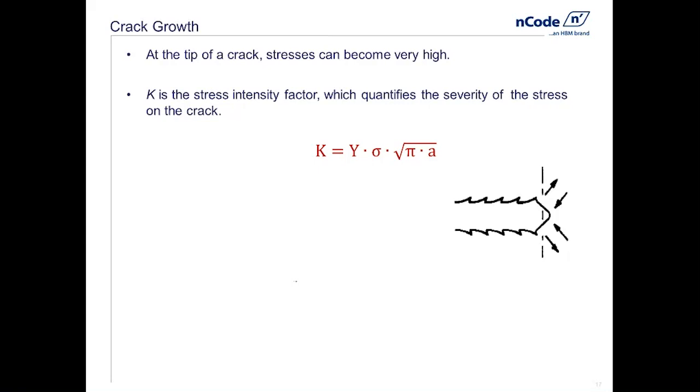which doesn't help a whole lot. If you thought that would help, at some point you should go to your director of engineering and say, I was looking at this crack in this part, and I calculated the stress on the crack tip, and I think we got it all figured out. It's infinite. And then you'll probably get a weird look like, okay, so what do we do about that then? And you'll say, I don't know, but it is infinite, trust me. So elasticity theory falls apart here for us, and we have to approach this with a fracture mechanics methodology instead.